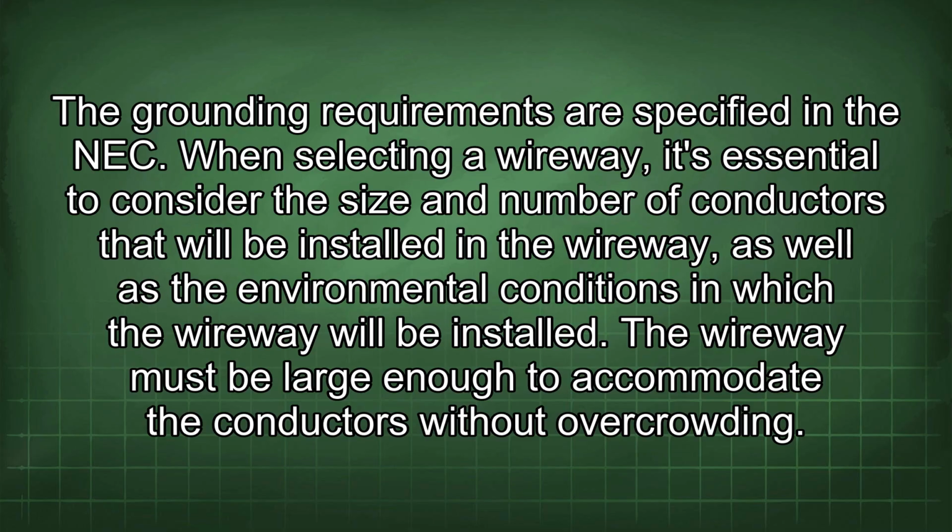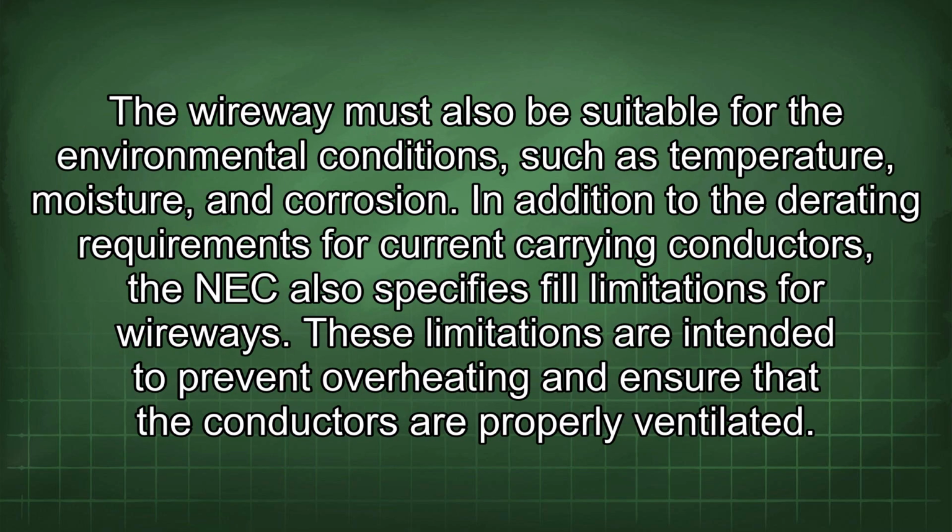When selecting a wireway, it's essential to consider the size and number of conductors that will be installed in the wireway, as well as the environmental conditions in which the wireway will be installed. The wireway must be large enough to accommodate the conductors without overcrowding. The wireway must also be suitable for the environmental conditions such as temperature, moisture, and corrosion.